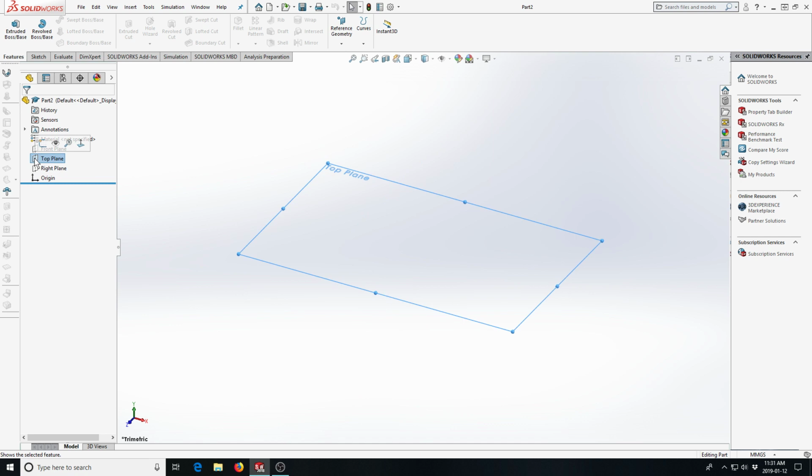So you can just left click to select it and then go to the little eyeball there and show. And so you can see that it shows up as being solid and blue in the menu on the left, and you can see the plane even if you're not selecting it. That's helpful. If you want, you could also maybe make the front plane visible. There.